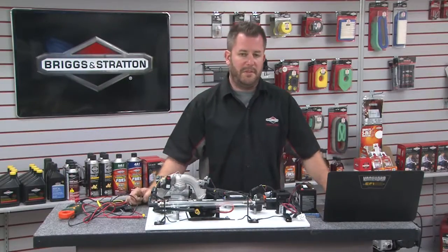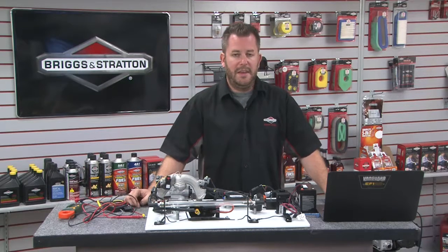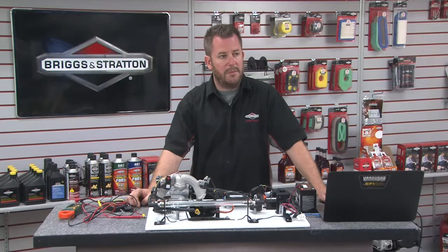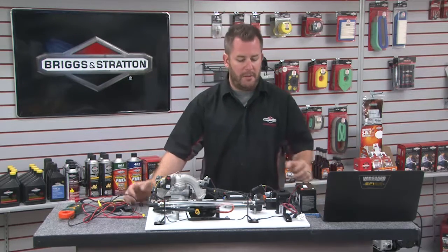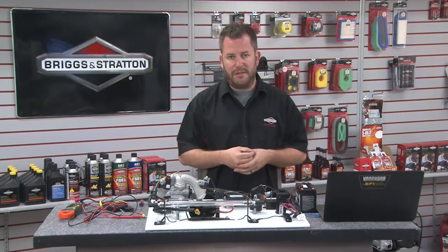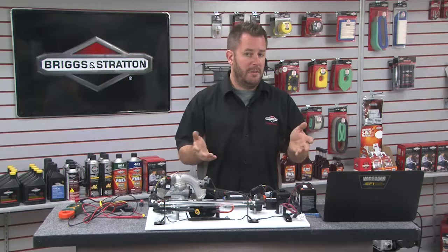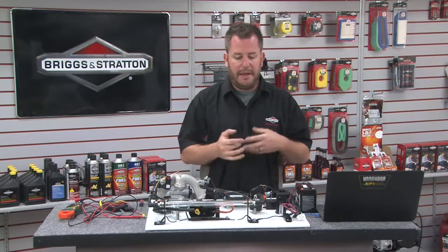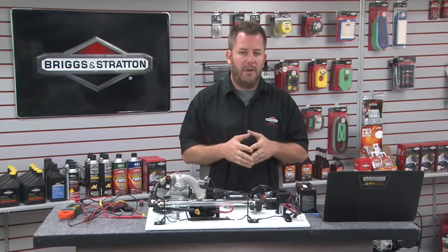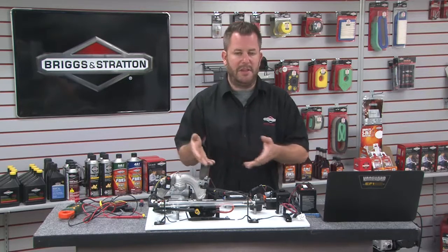All right, welcome to our first question and answer session here. All right, our first question comes from Larry in Colorado. He asks, a future program concerning the connection of an engine trouble light would be helpful. Larry, I think you're referring to the malfunction indicator light or a service engine soon light for this thing. That would actually be a really good exercise, and it is a pretty easy process to do. Really, you're just hooking up power to a light bulb, and then the ECM runs the ground there.